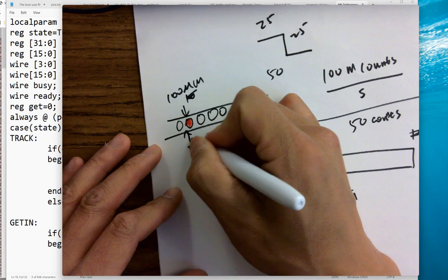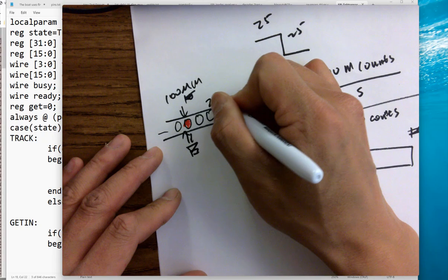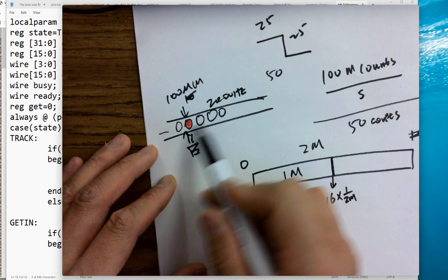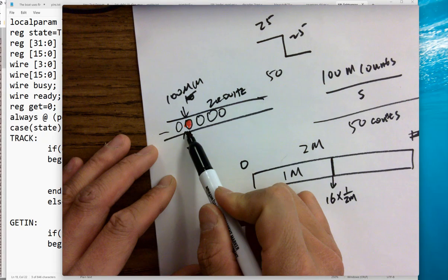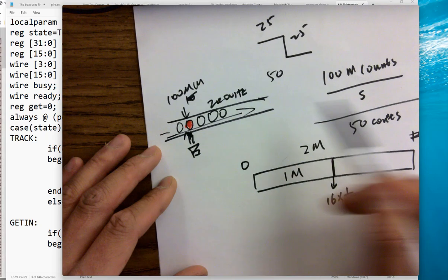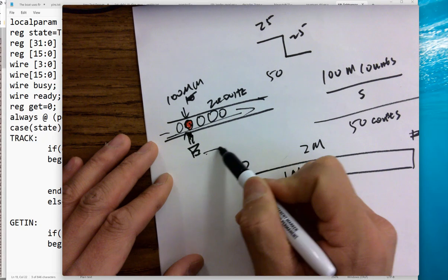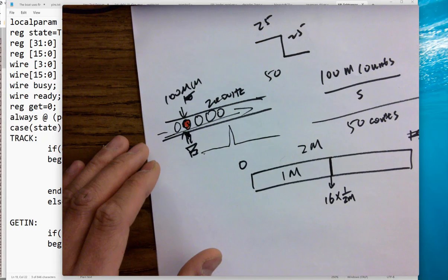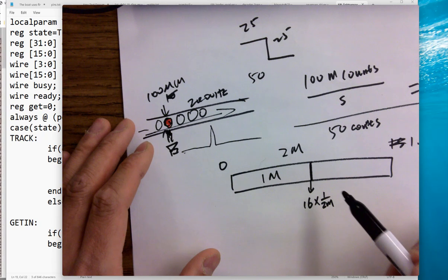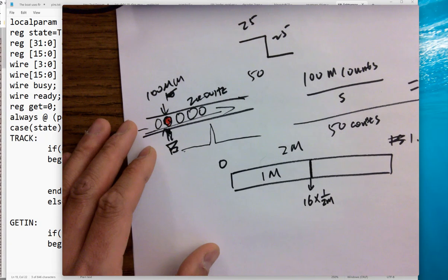We run the droplets through this channel really quickly, at 2000 hertz, for example, which means 2000 droplets are going through this detector every second. It's really fast. Whenever a positive droplet shows up, it's going to show you a pulse. In that case, you definitely want to increase the sampling frequency of this application. This is changing really fast, 2K hertz.